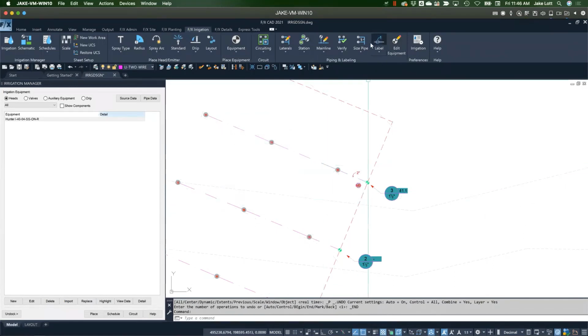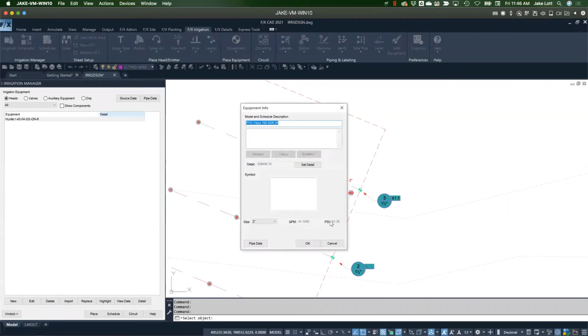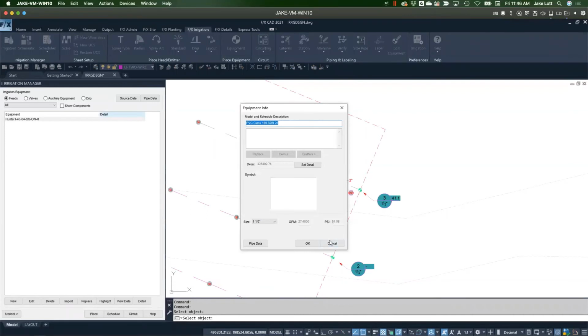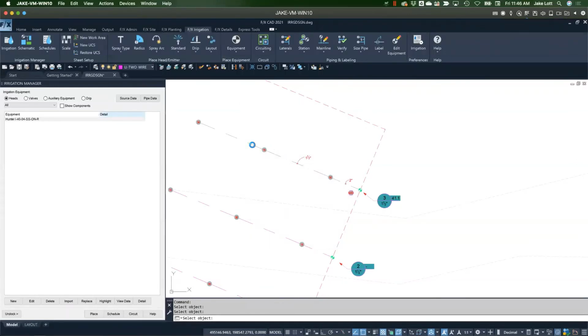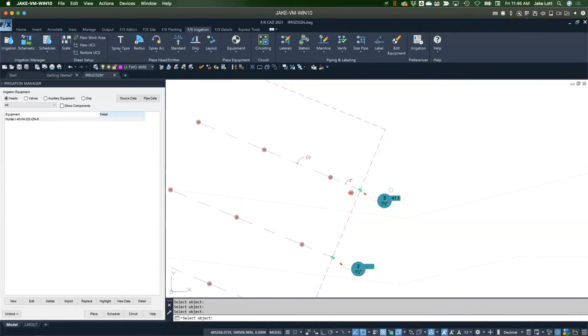And we're good. And you can see here too, I don't have minimum pipes labeled there, but you can see that this is where the transition was. So if we were to look at any part of this, this is where you have these tools available to you from an analysis standpoint to see what kind of losses are coming out of that specific part. So the further we move closer to the end, the less additional friction loss is happening, of course, but it's accounting for all of that there.